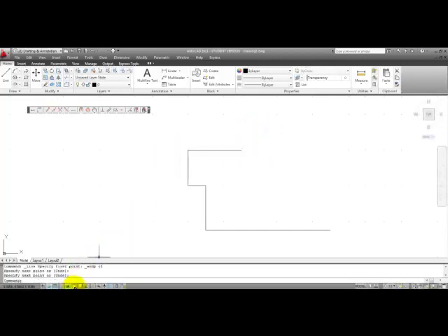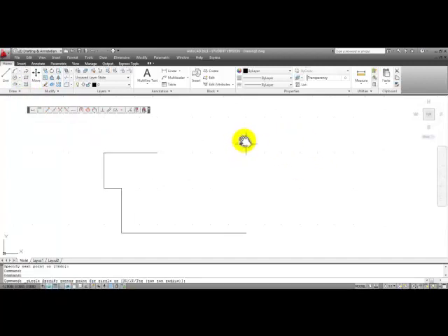We have our object snaps off at the very bottom left corner next to polar tracking, and we're using here the object snap overrides. We can now start the circle center radius command, and at the top of page 3-23 we're going to move our cursor to the point 11.5, 6.